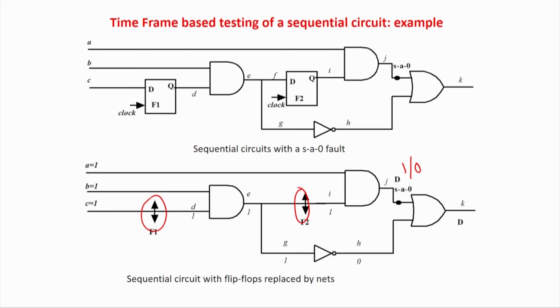That is going to give you the value of D over here. Then I have to propagate the value at the output, so I am propagating it. So sensitization is done, propagation is done. Now D is the OR gate, so I am justifying. So D is the OR gate, so I will have a 0 over here, this one, NOT gate 1. Of course, this is an AND gate, so I require both 1 1 here. So I will require a 1 over here. So anyway, this is a 1, the 1 required. Fortunately, there is no conflict.